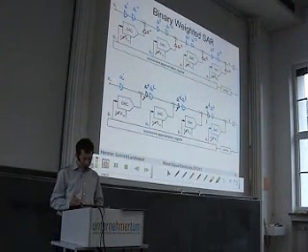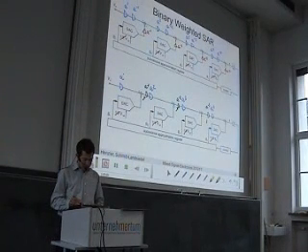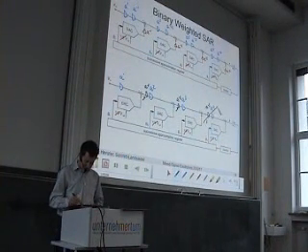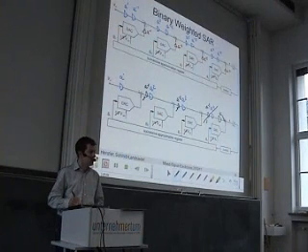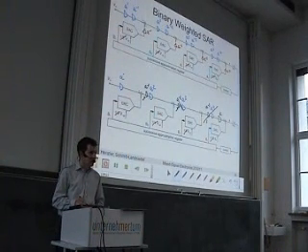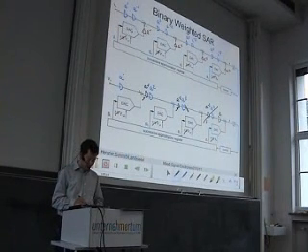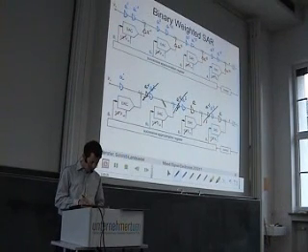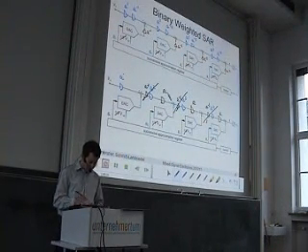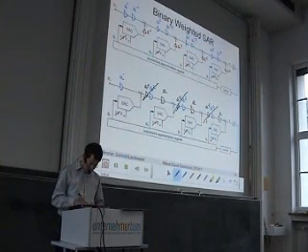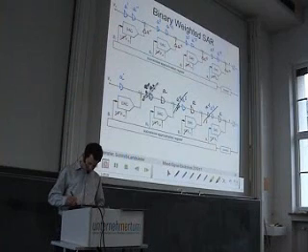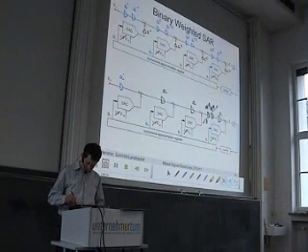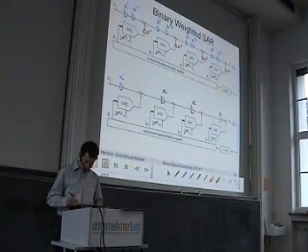And here you can see we have a to the power of minus 3 scaled by a to the power of 4. So we can also say we delete this and replace it by a simple a. Here we have a to the power of minus 3 times a to the power of 3. This gives a single a, and we remove this. And the same here, we remove this and have a simple a. And now the circuit looks like this. We have only the scaling factors in the signal chain.